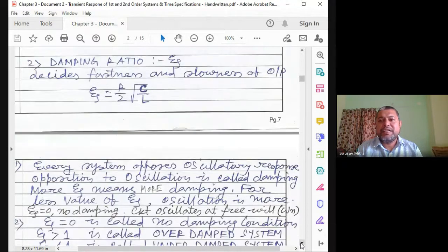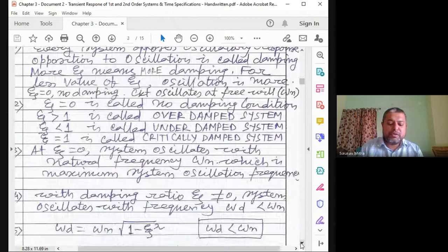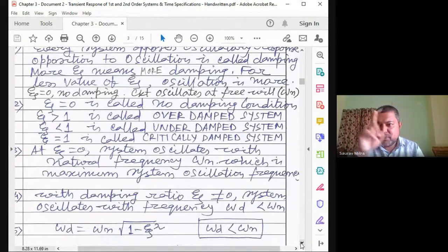What is that thing called? Critical damping. Critical damping you will find waveform will start like this, charging. Output we are taking across capacitor, so it will start charging like this and very fast it will go up and stabilize. So this is the standard response, but very fast it will go, like this and stabilize to 1 volt. And when it stabilizes to the final value, then you are supposed to find out what is the difference between input and output.